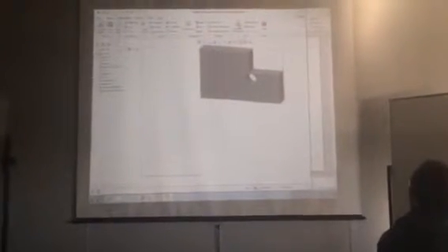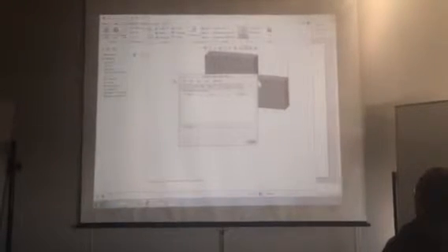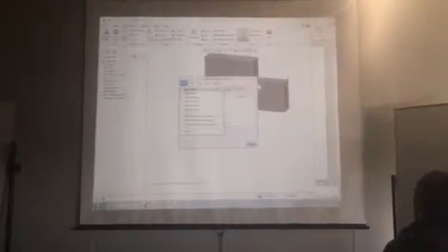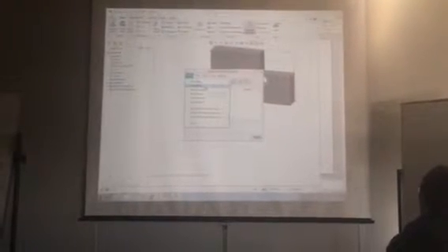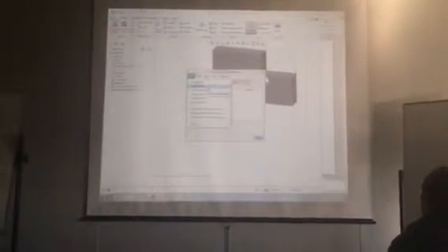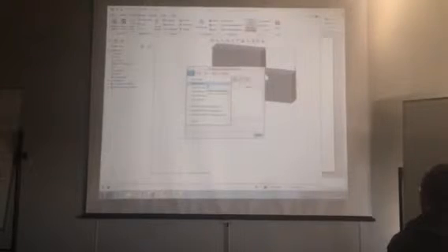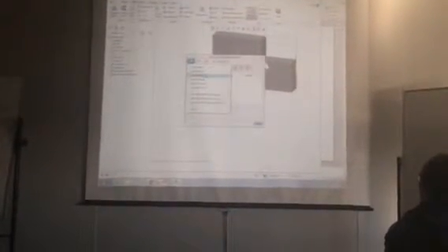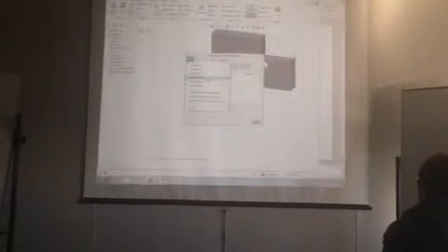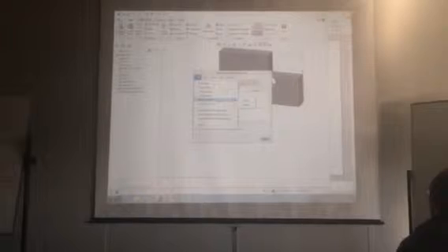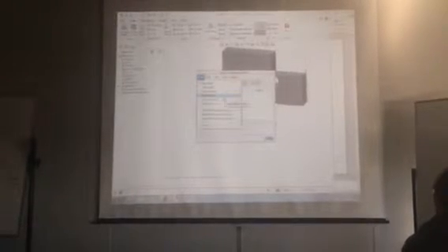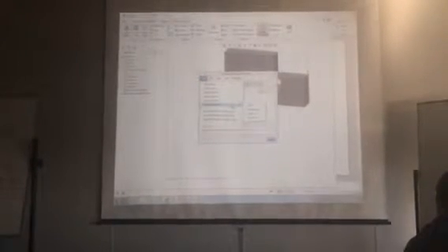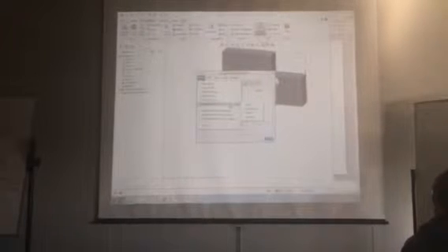And now I'm going to go to analysis and studies. So you can see the kind of studies you can do. You can do a static, which is what I'm asking you to do. You can do a modal to calculate the natural frequencies of something, which could be useful perhaps for some people for projects. You can do buckling, fatigue, pre-stress, dynamic. Creo isn't so good at dynamic, nonlinear problems. It's not good at all.